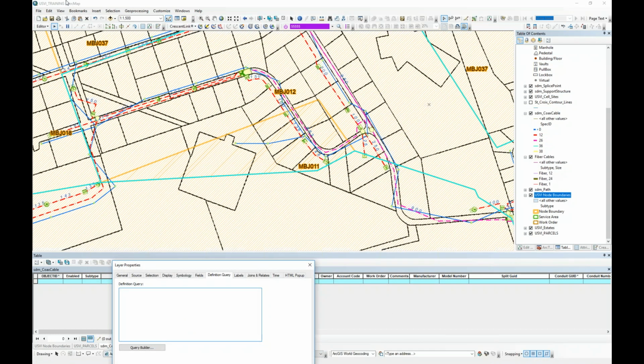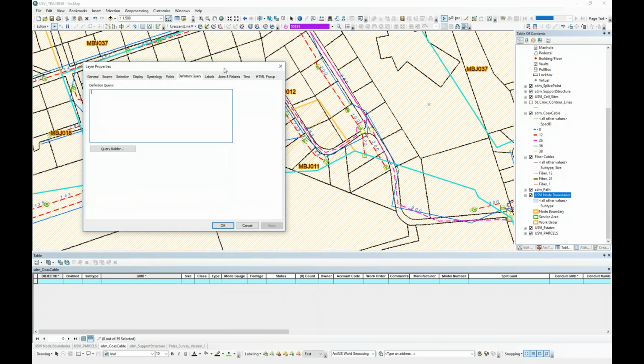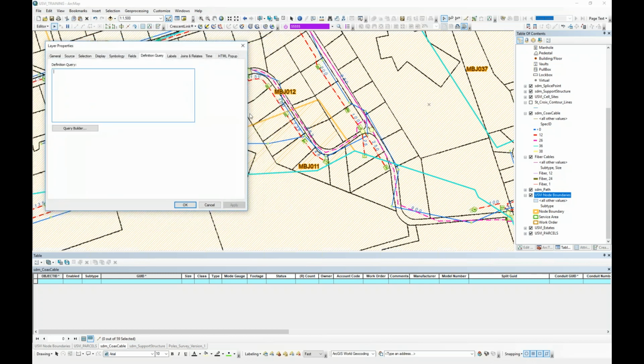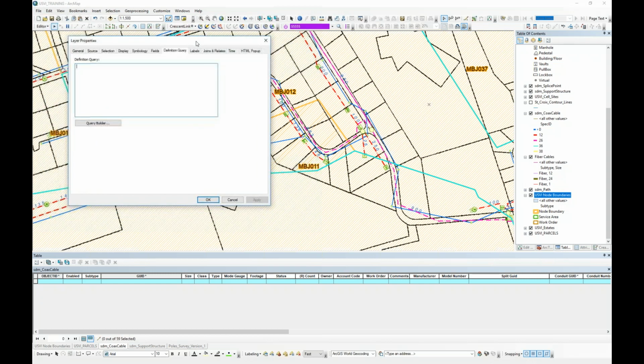So when you change the node boundary, do you want to change all the elements within that boundary? If it overlaps, yes, you would. If it's say like this piece of equipment is in this node, but then you change the boundary and then it's not, you would have to change that. But you can easily do that by selecting that new boundary and selecting everything in that boundary, and then you change the node. So you can mass select everything based on a boundary.